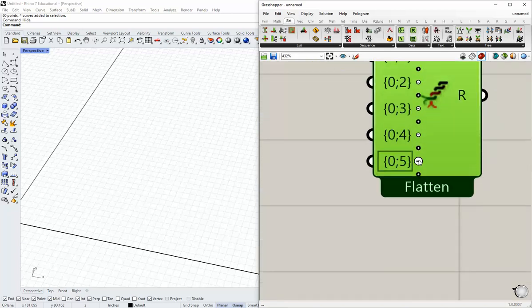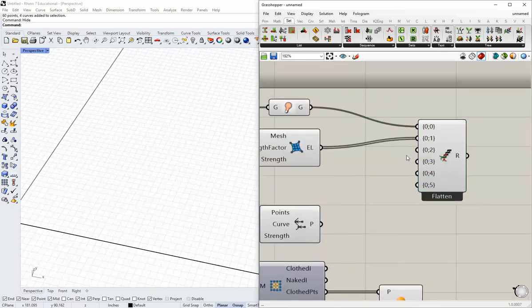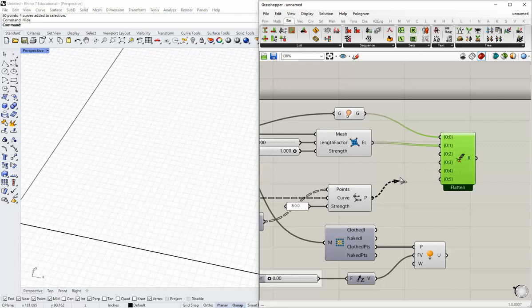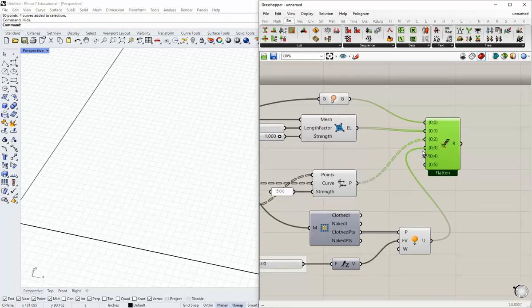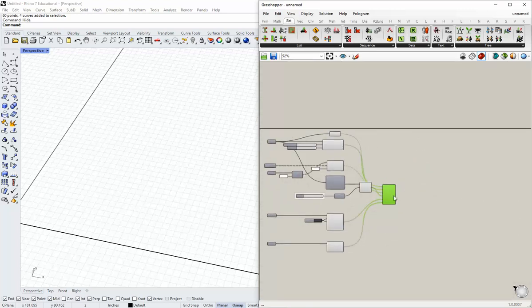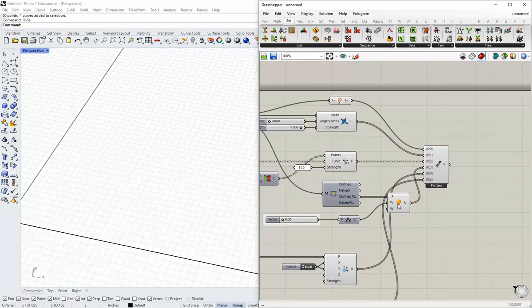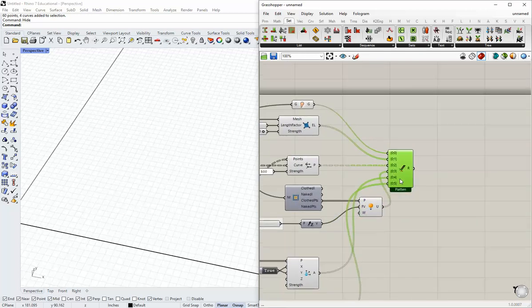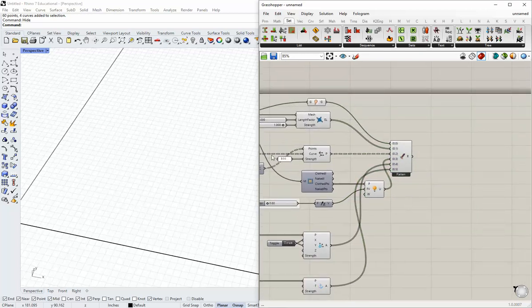I'm going to add a bunch of inputs here, and you can go down the line adding all your inputs nice and neatly into this Entwine component. So all the goals are now set into one little area, and if I need to make any changes, this is a good place to do it. I can then mix and match goals as I feel the need to.